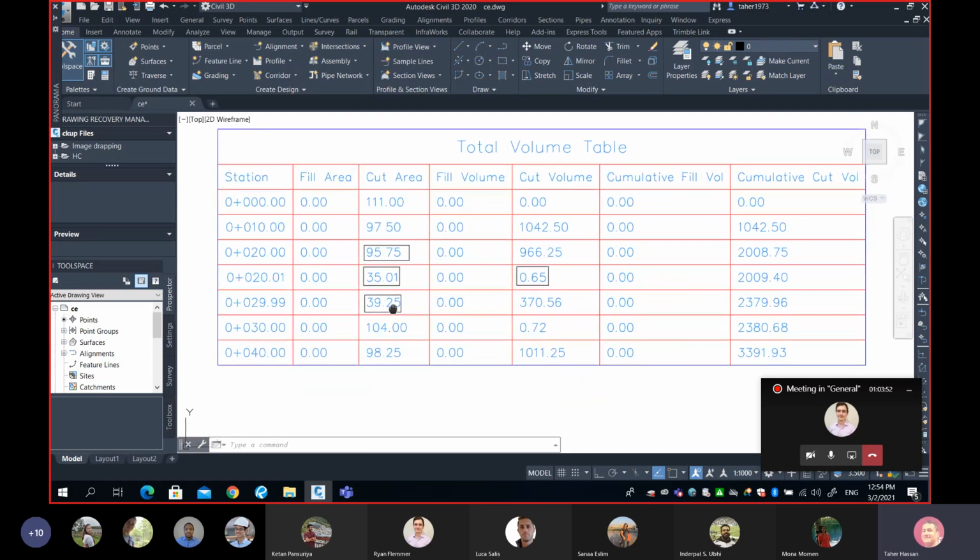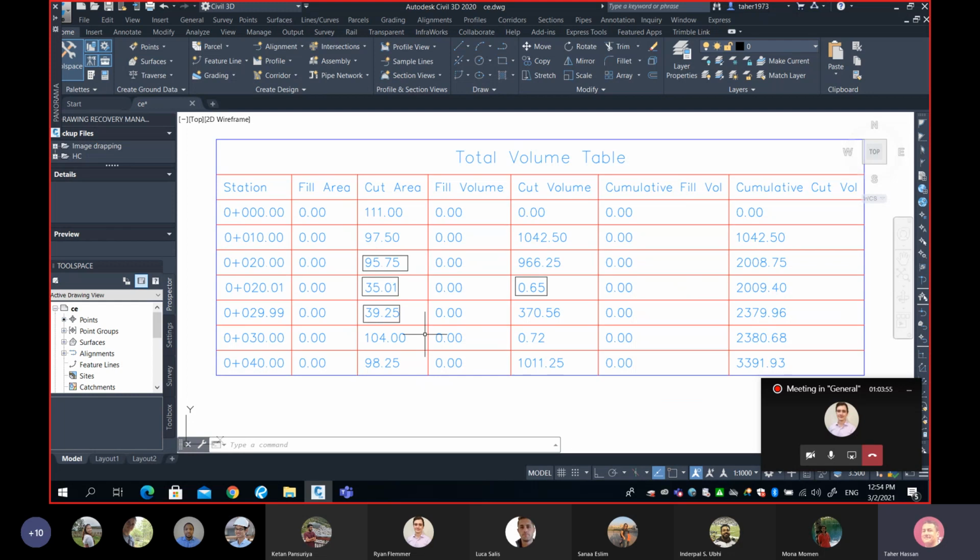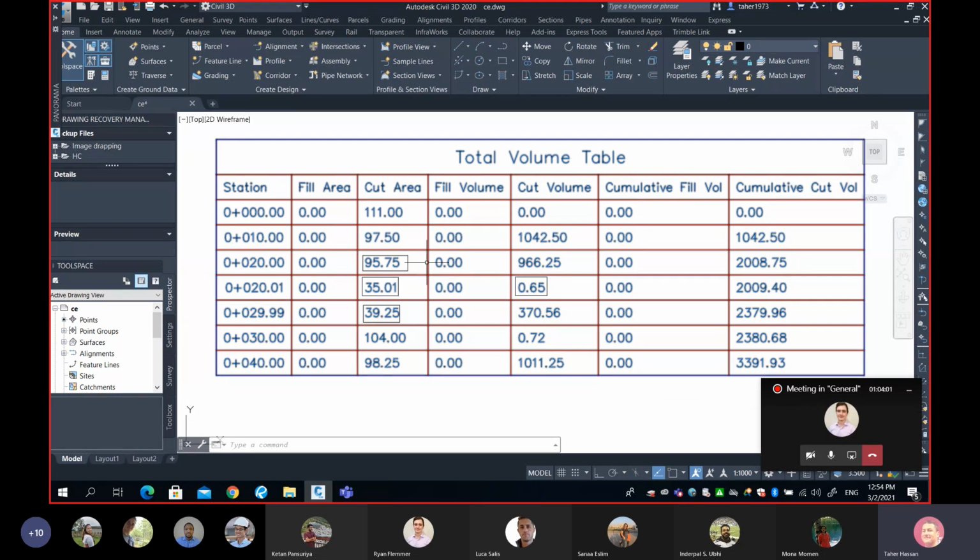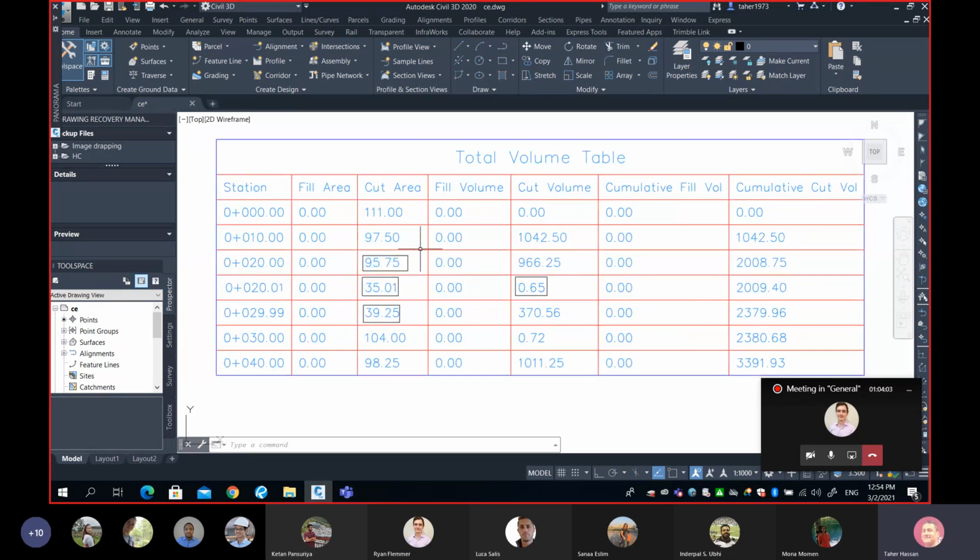like this one was easy. I asked you to get your calculator and follow me. So that was only for education. You can follow exactly what's happening in this table. If you plot the Prismoidal, then you have a problem. Because remember, there is a middle section and you have to multiply d over 6, which is 10 over 6, times A1 plus A2 plus 4 times the area of the middle section. And that's why when I teach, I always use the average area because it's easier for my students to follow me on the table. Does it make sense? That makes sense.